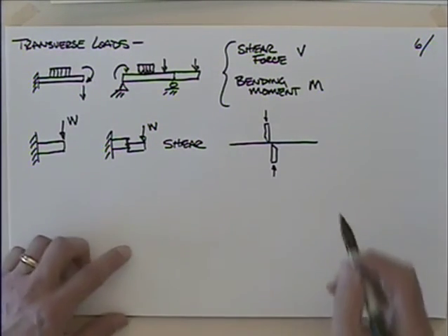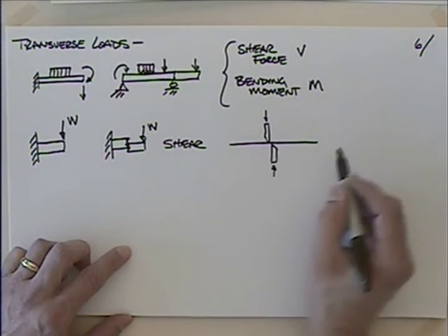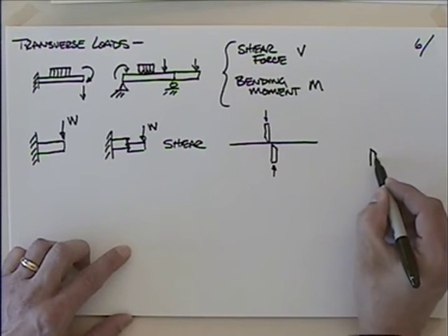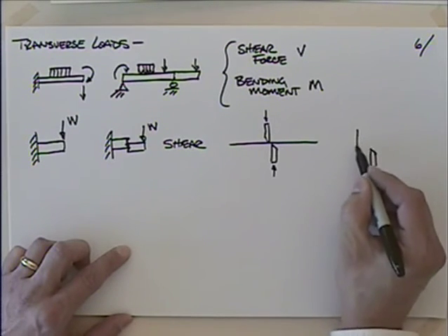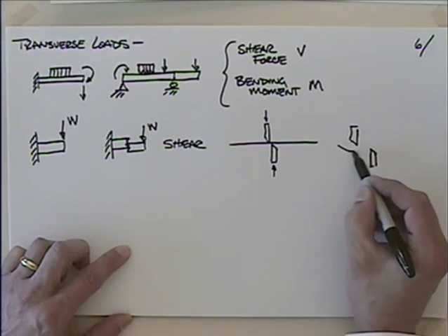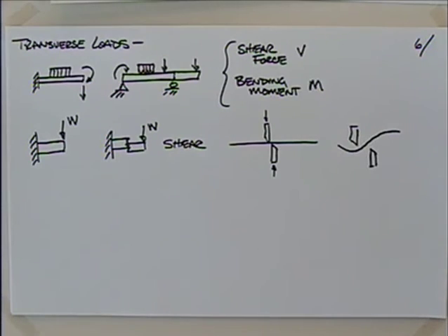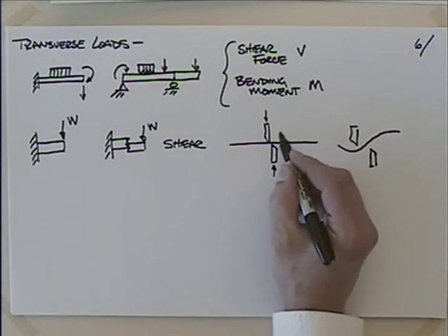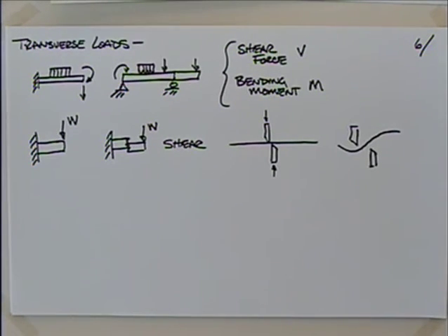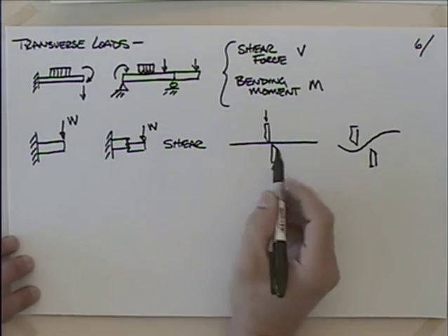Now, if your shears get a little bit worn out and get too far apart, so your shears look something like this, what happens? Paper bends through there, doesn't it? So in the first case, we expect the paper to fail in shear, whereas the paper in that case fails in bending, which is quite frustrating if you're trying to cut out paper dolls or something. Okay? Questions with that? Okay. So that's shear.